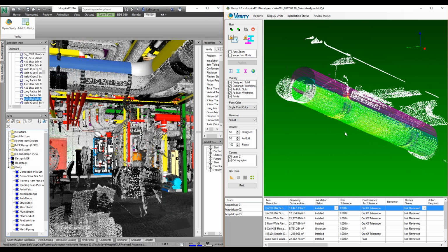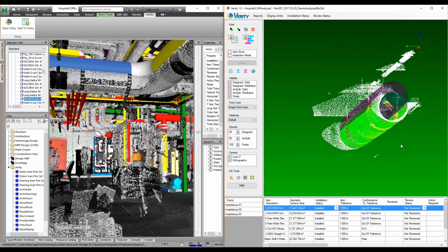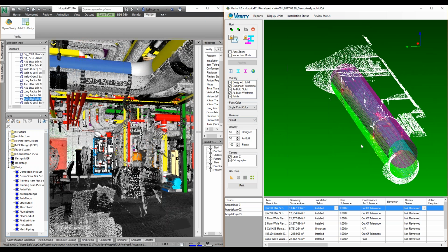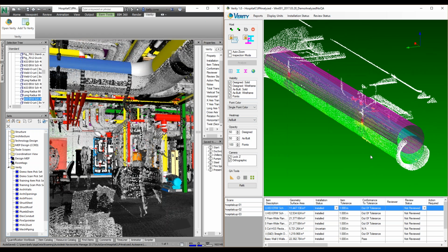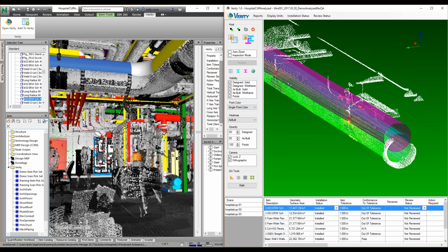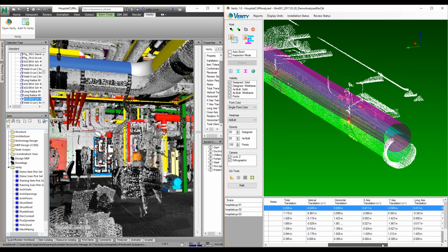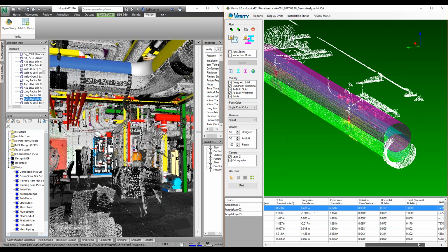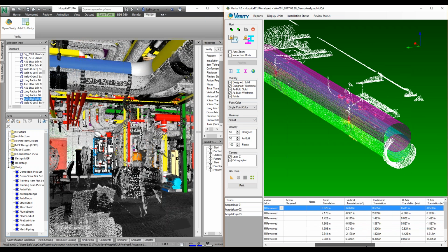The as-built one will let you understand if there's some amount of deformation by the point coloring of the shape, so that would be things like camber or just sag. If either of those were present, you would see a gradation of color along here. We do not provide numerical results for camber or sag. Right now we're primarily focused on how the object is moved, and so you'll see here for this object we've got a lot of different measurements comparing those 2 pieces of geometry.